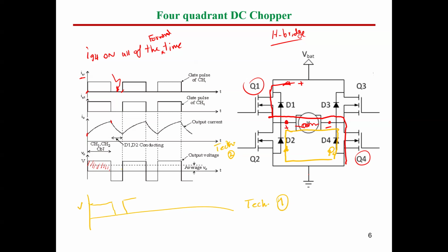If you compare the output volt of the two techniques, you will find that during a complete cycle, from here to here, the current is going to be the same. No change in the current, because the current will discharge either through the other MOSFETs in the other operating region, or through the diode. So the current will flow. No problem with the current.